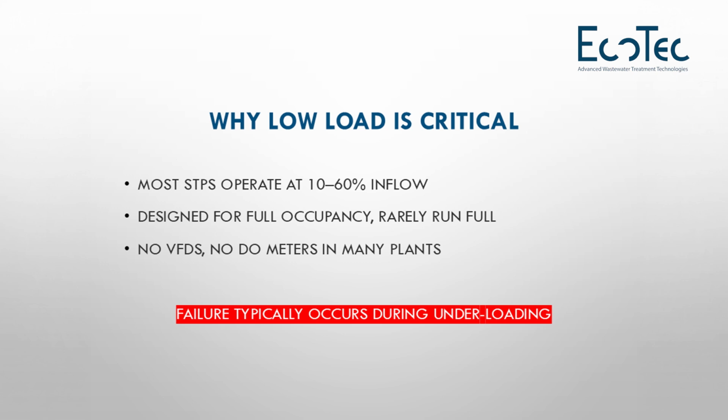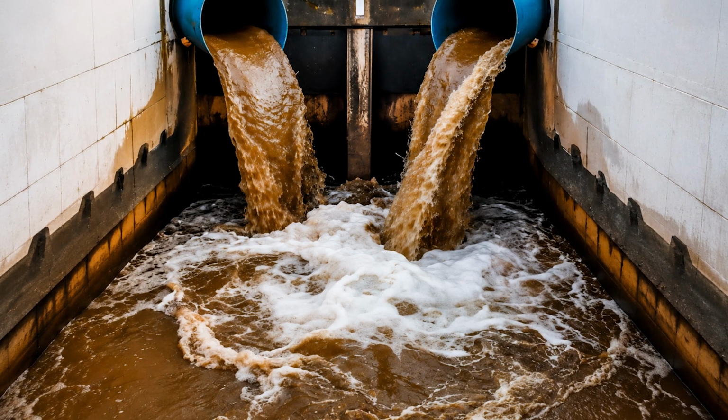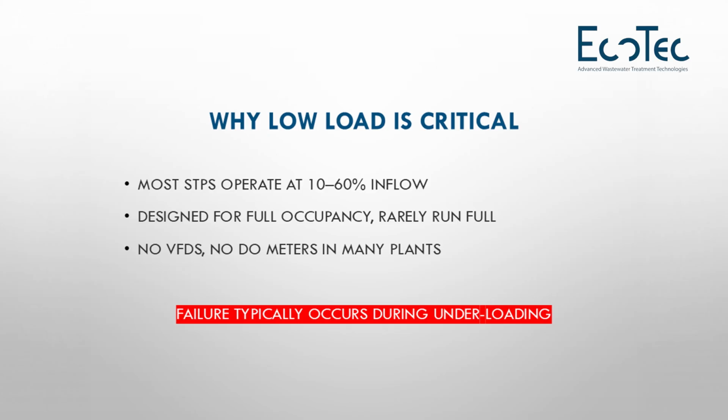Yet, blowers run continuously, pumps run continuously. Maybe the pumps have float switches which go on and off depending on the incoming water. Operators blindly maintain MLSS targets. Failure rarely happens at overload. Failure happens during underload. And these are facts.